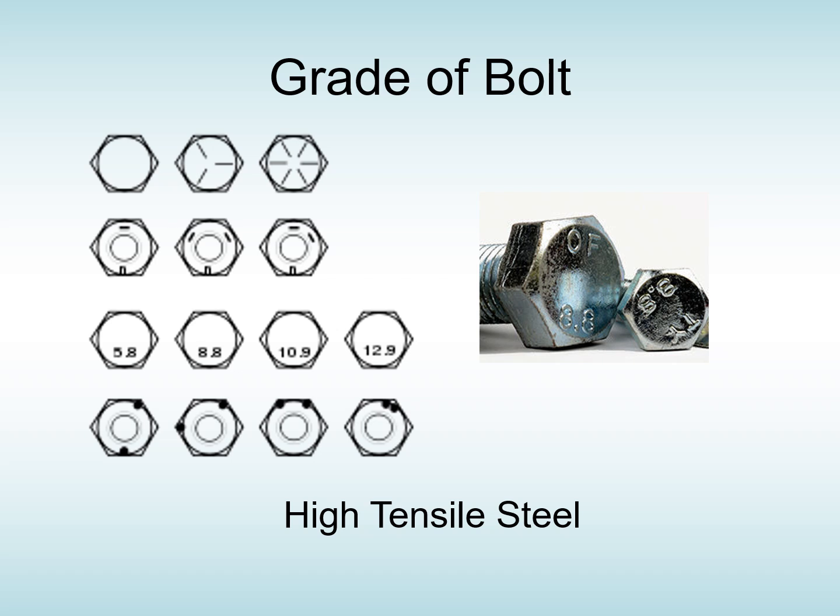So let's move on to the grades of bolts. They are generally all made of high tensile steel. And how do you know what tensile steel they're made of? Well, if you look at the heads, these ones here are generally American type. These ones here, again, can be American. The reason that we use a lot of American bolts is because a lot of refrigeration started in America. Here we have the more common ones used in the UK, and the most general one is an 8.8 bolt, but it goes up to 12.9.